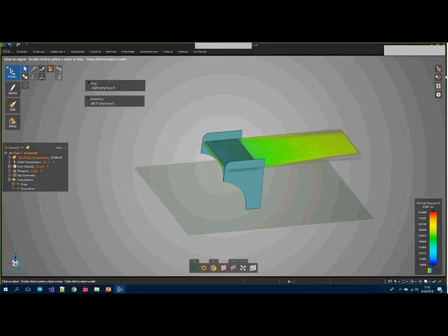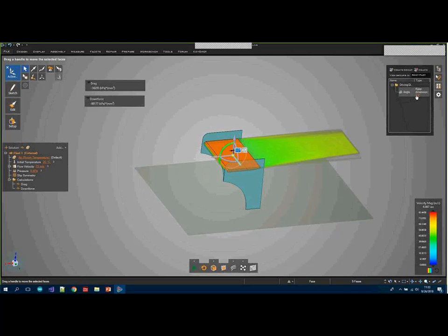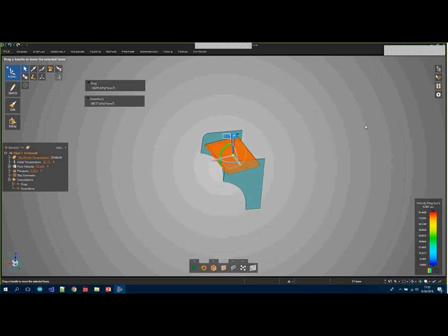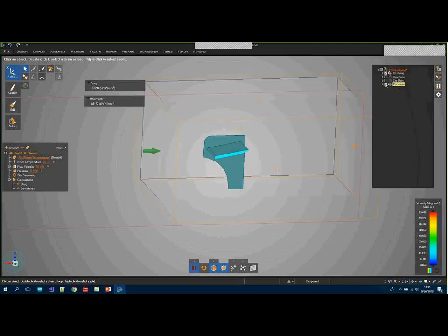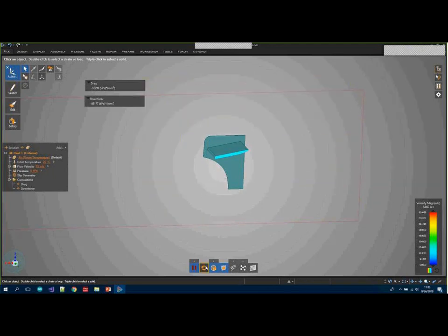So in this case, what I have is the ruler dimension over here, and you can see that I can tweak it by entering a value. So maybe I'll put in 10 degrees. And the wing will change its orientation. Now, if I show those results again, it should give me the updated results for the flow. Right, so there's that. We can restart that or update the volume.